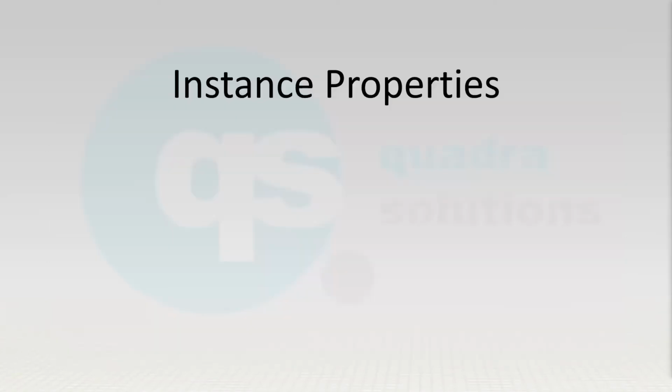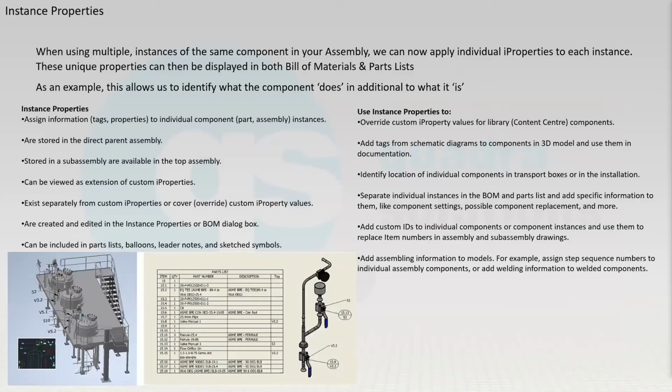Instance properties allows me to assign different information to each occurrence of that file within this particular assembly. The benefit of this could be, looking at some of these screenshots, we've got the same valve twice, but they're doing 2 different jobs, or they've got different tag numbers. We might have the same tank 3 times. We might be using the same gearbox 4 times.